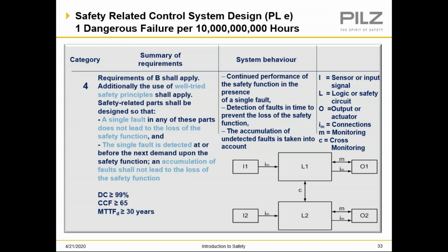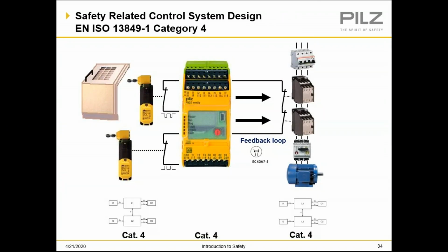So this circuit would see that fault. Say you had an e-stop with dual channel. One channel gets welded shut. It's going to break it. It's going to take you to a safe state, but the CPU is not going to let you reset the safety circuit until you clear that fault and that welded contact is fixed or replaced. And there's what that circuit would look like in redundance.